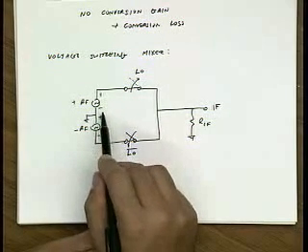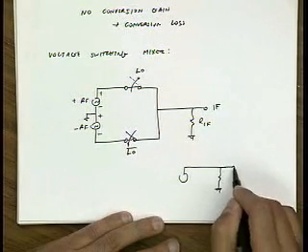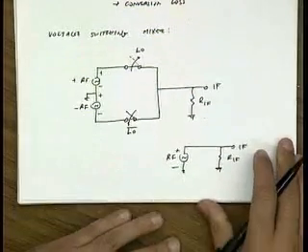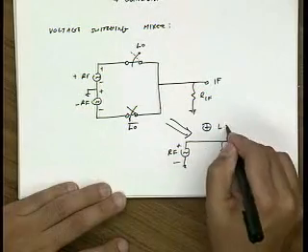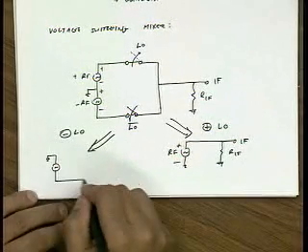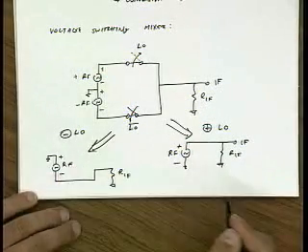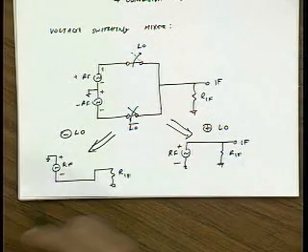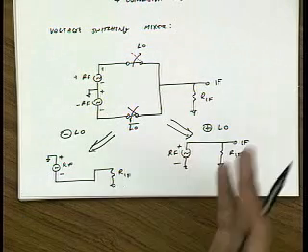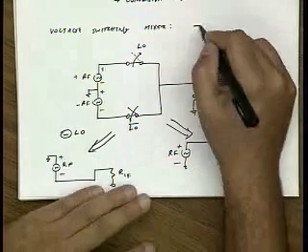And this is plus minus, this is plus minus. So you can see that during the plus LO cycle, the equivalent circuit is just RF applied directly to my IF. Right? During the negative LO cycle, I have this side grounded, and then this is connected to RF. And so we can see that this circuit is very simple. It just multiplies the RF by plus or minus 1 at the rate of the LO period. So it looks a lot like some of the other mixers that we've seen before. Okay? So what we need are good switches.